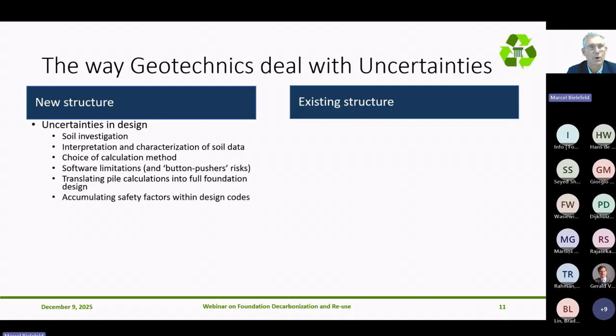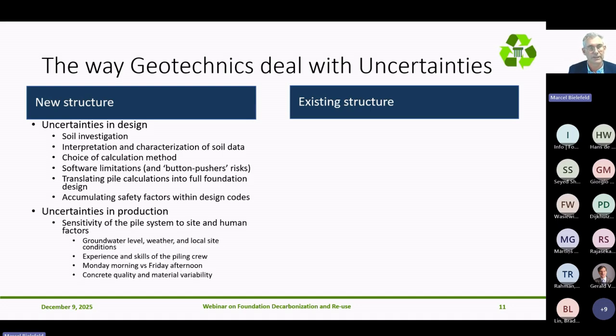So if we split it in more detail, and I'm quite sure you're familiar with all those uncertainties, and you can even add your own uncertainties to that as well. But if you look at the design process of a new foundation, you have to deal with all the aspects of the soil characterization and the transfer of the soil data and soil investigation results to pile factors. The use of software, where some users are only pushing the buttons, not even aware of the engineering judgment needed to do proper foundation design. And then in the end, in all the design rules, there are safety factors, and quite often safety factors accumulate and add up to a certain design.